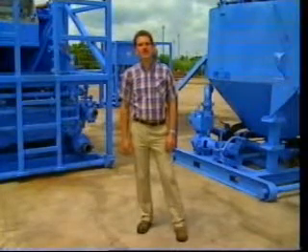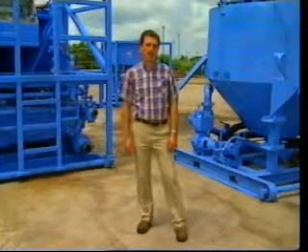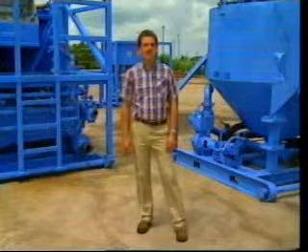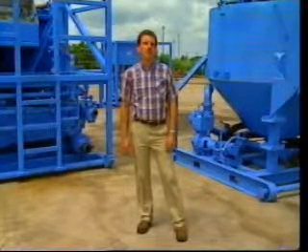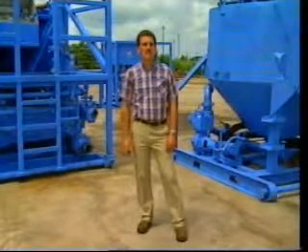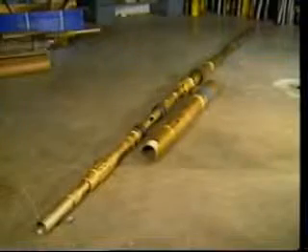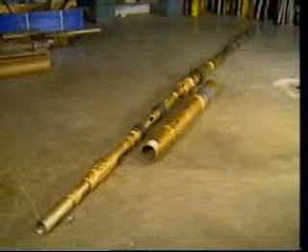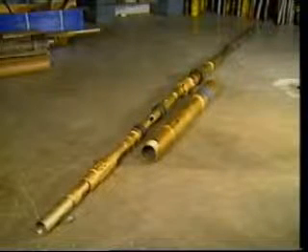There is a wide range of cased hole gravel pack assemblies available. Multiple completion intervals, thick intervals, and deviated wells are situations requiring special considerations and often special types of gravel pack assemblies. The open-hole gravel pack employs the same conventional circulation techniques.